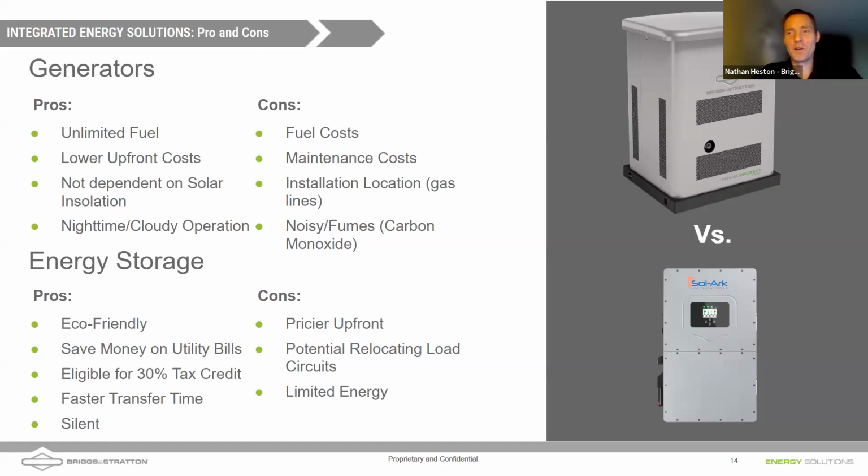I've seen some customers that are in very cold locations talking about generators not running, of course. But the con is, of course, generating electricity with diesel or propane or gas can be expensive, right? It's expensive, and Daniel, you'll get into those costs a little bit today. Also, you have to do engine maintenance, right? There are engines to take care of. There are batteries that will be needed to change over the years. Installation location, you are going to be limited in where you can put this. You don't want to put it under your bedroom window. And we're going to talk about where to put it. And of course, they're a little bit noisier.